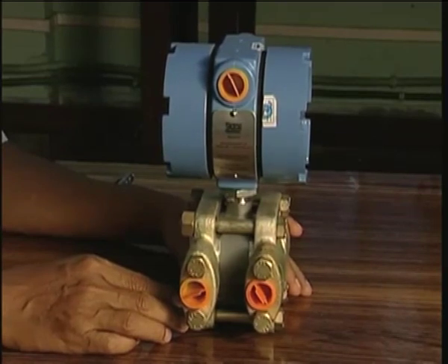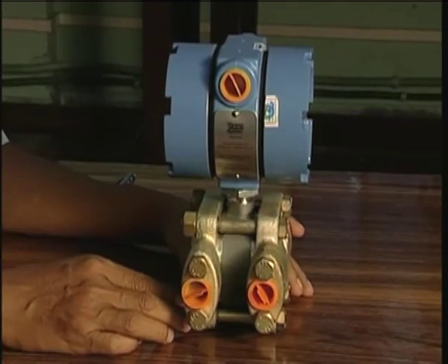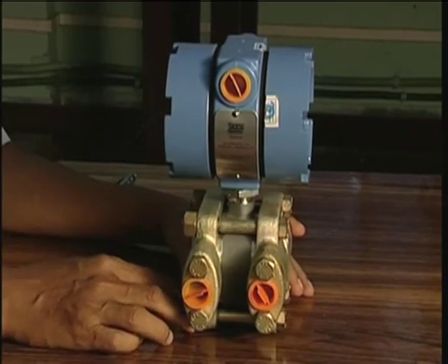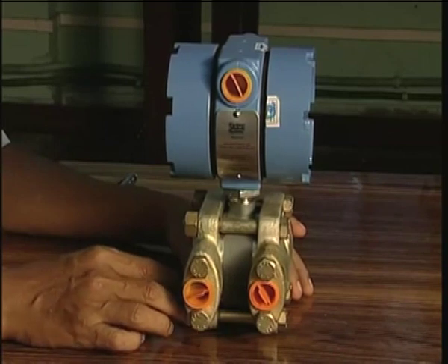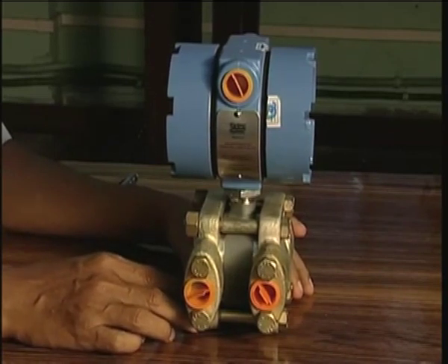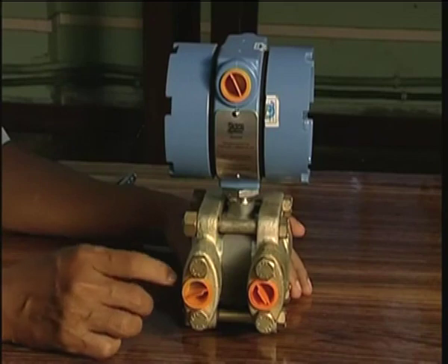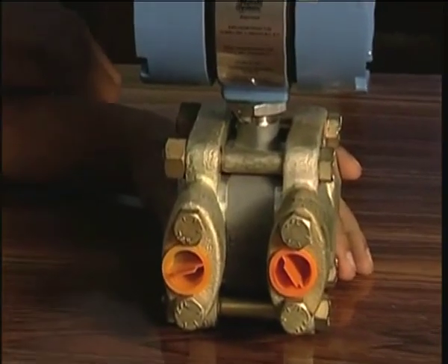We have seen in the class that we showed a manometer, by which I am measuring the pressure. But unfortunately, in an actual process, I need some instrument or equipment which will give a signal that will be transmitted to the control room. For that reason, we need some electrical output. So, in the case of this differential pressure transmitter, there are two pressure taps, one upstream and another downstream.